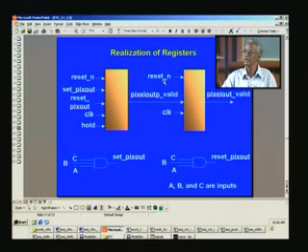And for that, a pixel will be output at every clock pulse, and the clock rate may be say 50 megahertz or so. So that means you can process 1024 by 768 pixel color pictures, motion pictures, at 30 frames per second. And for that, you also have to have another signal indicating when that pixel is valid. And for that, I had to generate this one.